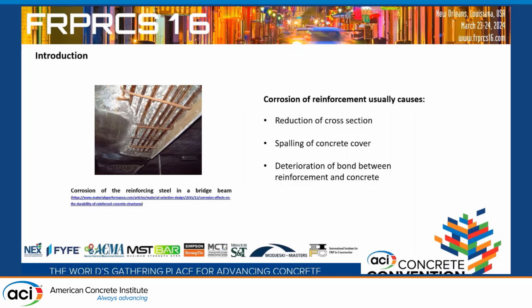So, about the deterioration of bond between reinforcement and concrete, I did some research about it, and then used CFRP to rehab these deteriorated concrete beams. The picture shows the corrosion of reinforcement, and we can see the spalling of concrete cover and some rust on the reinforcement.